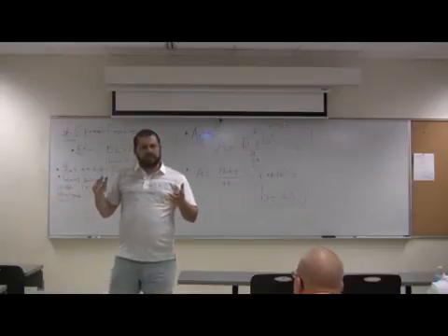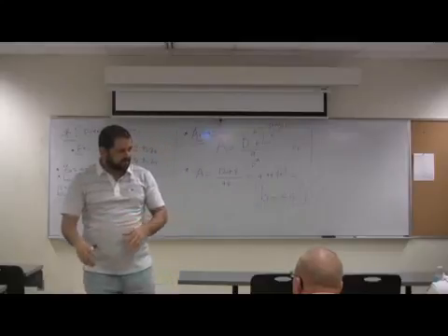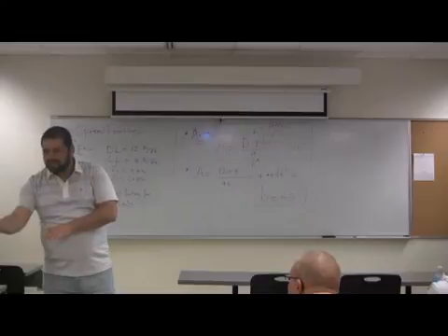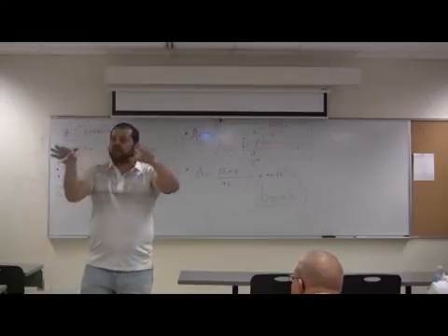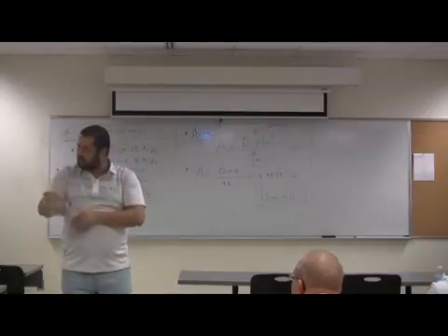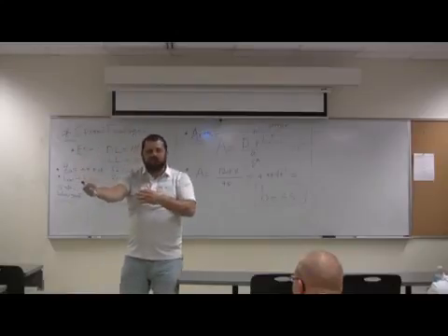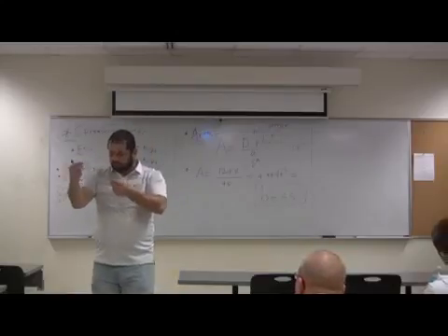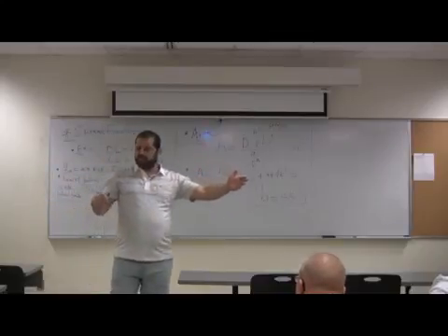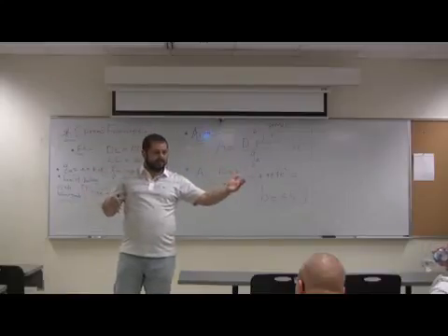You may say, okay, how about the same as the coarse aggregate? We did the bulk unit weight of coarse aggregate. You remember that container? You filled it in 3 times, rodded or non-rodded, and put it on the scale. If you take a 1 foot cube of sand or coarse aggregate as is, not the concrete, how much do you think? 98, 95, 100, 105. It depends on the size of those, which will determine the void. So for the soil, let's say 100. Sometimes it gets saturated, maybe a little bit more if it's saturated with water. But if we assume 100, okay?